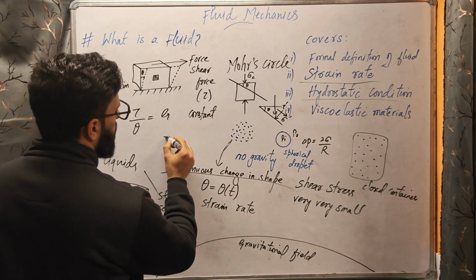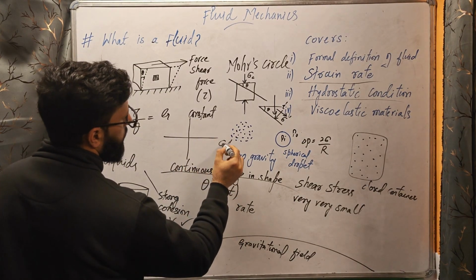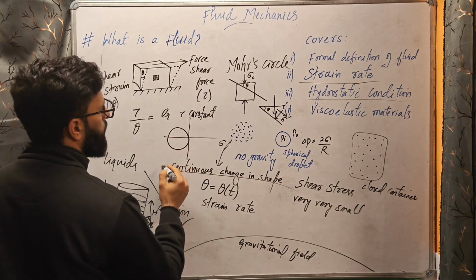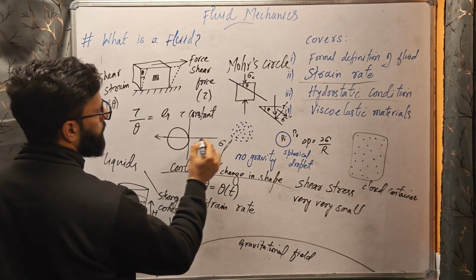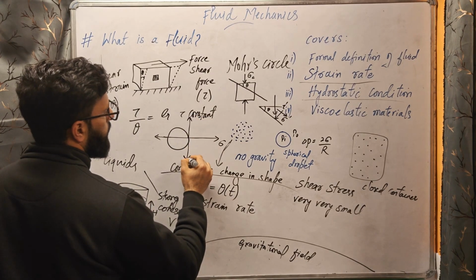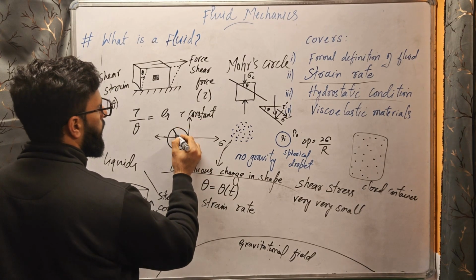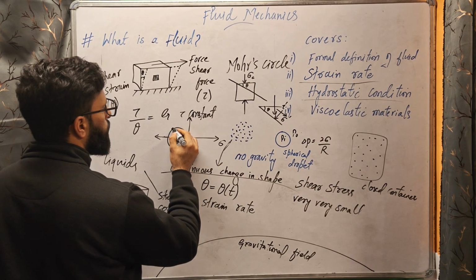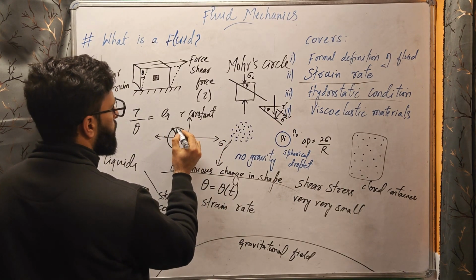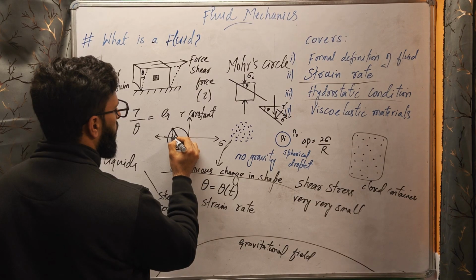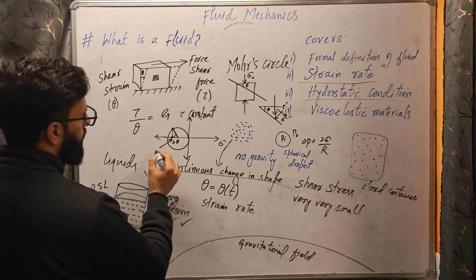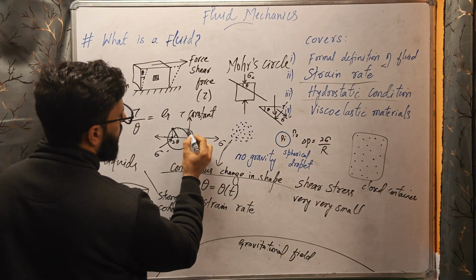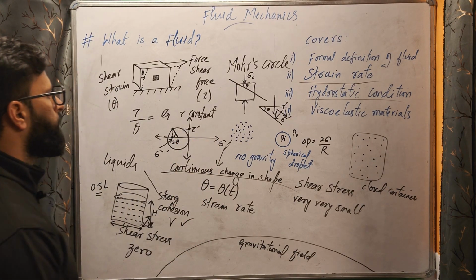And if we draw Mohr's circle like this, this is sigma and this is tau, so we have some kind of Mohr's circle like this, and this angle will be this theta, and we know this is twice theta, and we get this point where we have the sigma dash value here and the tau dash value here.